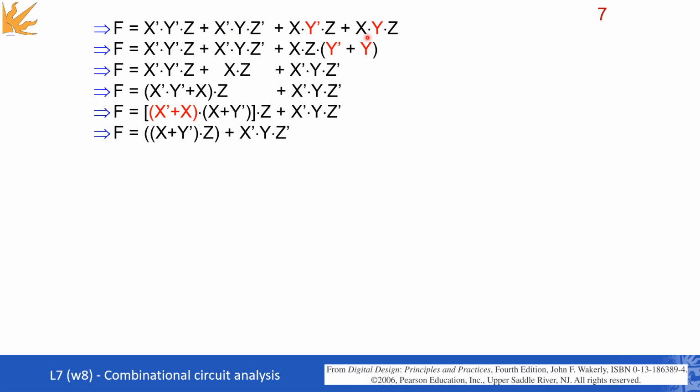Now, if this is the function that you get by having the sum of products, then with the usual tricks that you have learned in previous lectures, you will end up with something which is minimized. Now, quickly going through each and every line here. We first identify that we got a y dash and a y here, and that the common factors are x times z. So that leaves us here with y dash or y, which, as you know, gives us a result always 1. Now, in the third line, to make things more clear and more convenient, we move xz to the second position here.